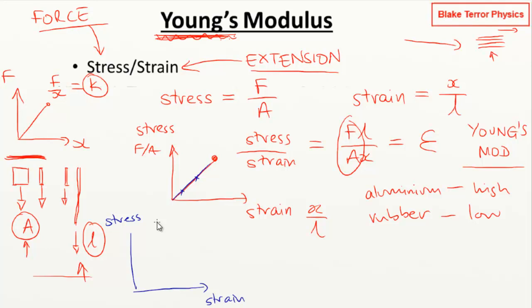So you're going to get a certain variability just because that's how materials are. You might have impurities or whatever in it. You might be approximating the Hookean region inside this extension, and then you've got the errors in your measurements. So we're approximating all of that and taking an average by looking at the gradient, rather than Young's modulus actually being a gradient. It is a ratio. So it's a slightly subtle point, but that's what I mean by saying we're using the gradient in order to work out Young's modulus.